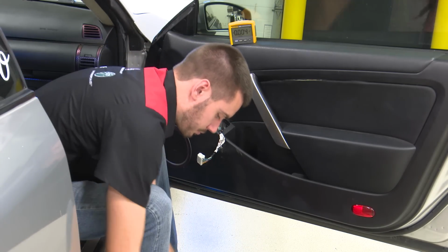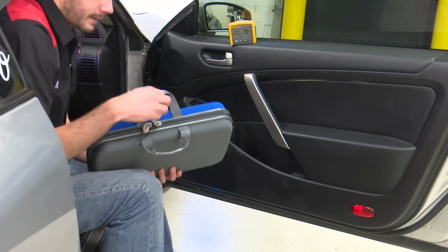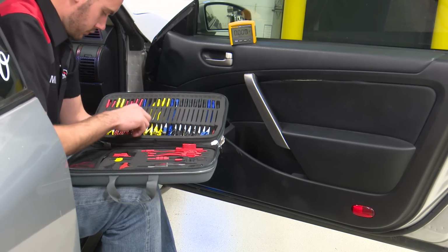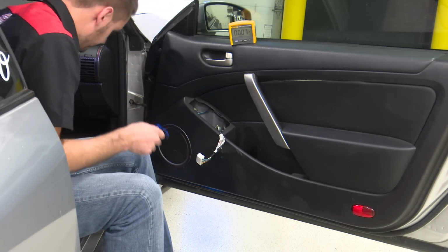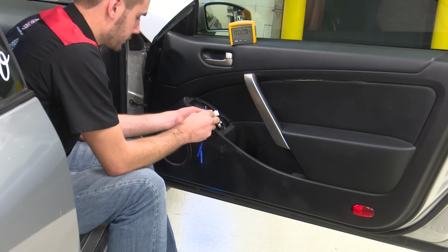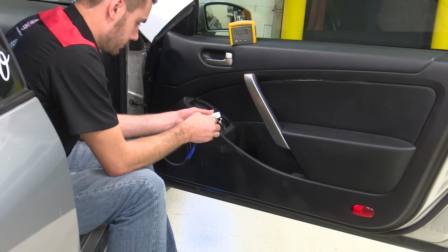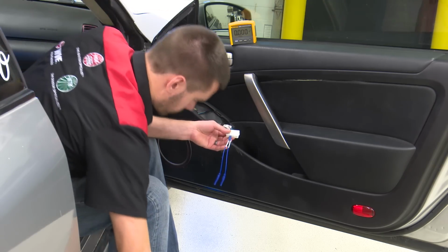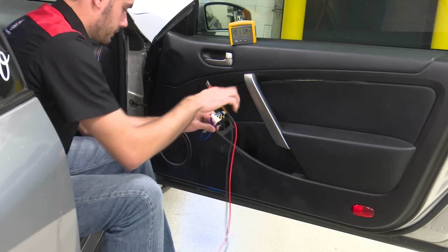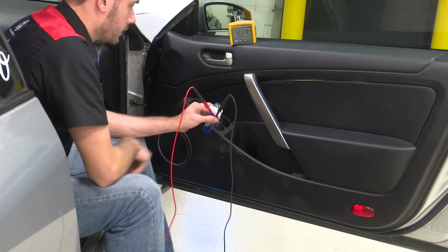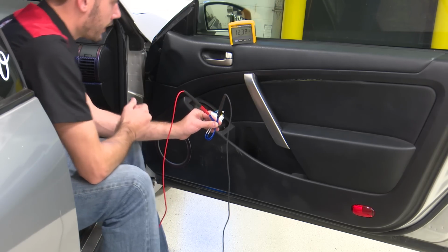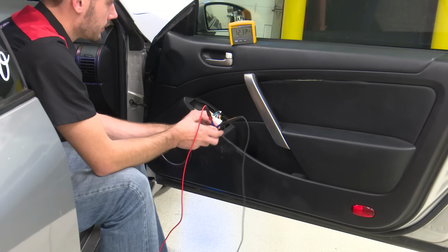Actually, let's grab some pins here, that way we don't possibly wreck our connector in any way. Probably about this size. And we'll just pin out the white and black wire on here. That's going to be our power and ground fed into the switch. So when I connect the meter to this, we should see battery voltage. Beautiful, 12.31 volts, so our battery's slightly discharged, but we're at just under battery voltage, okay?